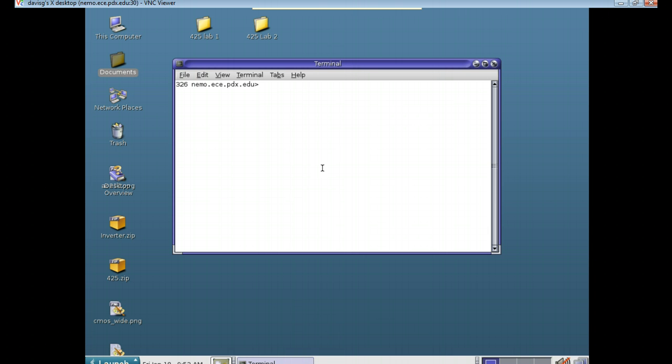When you first come in here, you will need to type this in, but once you've done it a few times, there's a very cool feature. It saves your previous input commands. So all you have to do is arrow up, and it will show you what you've previously typed in. The first one we're going to start with is cd Cadence610/. The cd being change directory. So you're going to change directory from your default home directory to the Cadence directory. Go ahead and hit enter.